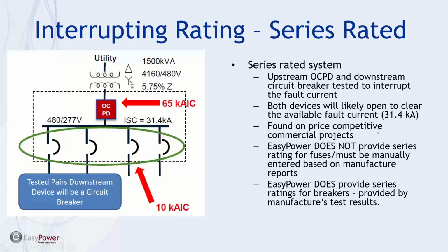So again, the bottom line is there's a potential for series rating to enhance the protection, but this needs to be a tested result per the manufacturer. It's not something we just can put into the software without that backup.